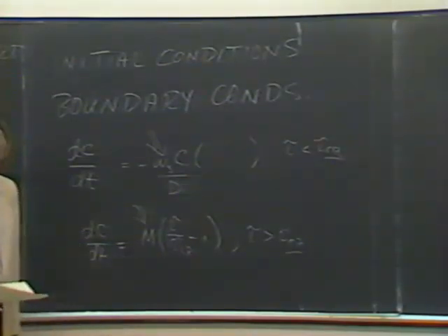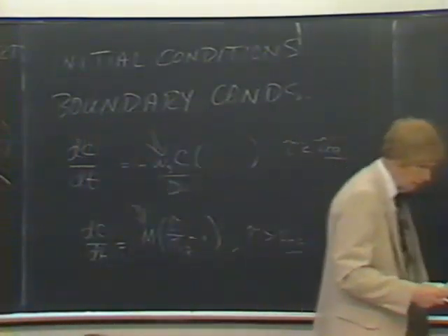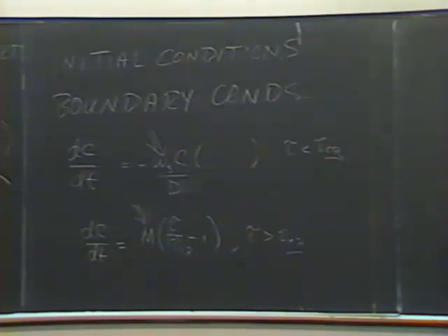During a tidal cycle, the material will deposit as slack water approaches, then during the strength of flow, it'll be taken off again. That's bulk erosion, typically. It may leave some on the bottom that is subsequently eroded. But the big changes during a tidal cycle are deposition during slack water, and then possibly resuspension, sometimes not resuspension. In a marsh, for example, you wouldn't expect resuspension. But in a channel, you'd expect some of the material that deposits to be resuspended again.